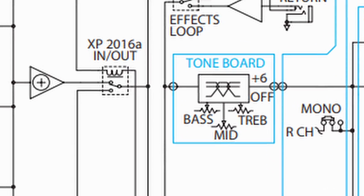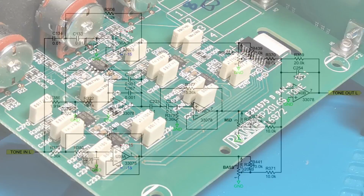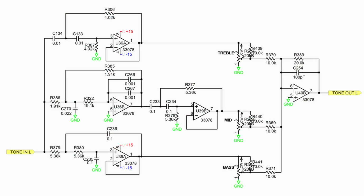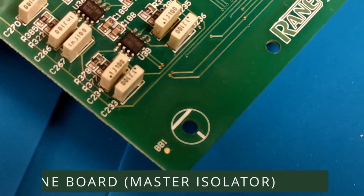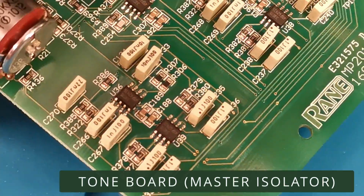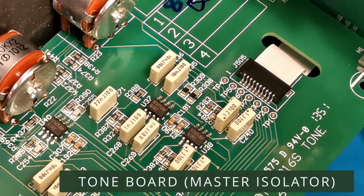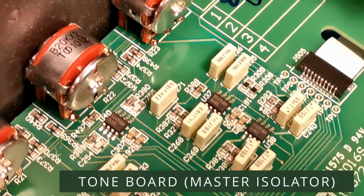It has an Isolator EQ control on the sum. The Isolator EQ is based on active filters that chop the audio signal into 3 bands and then sum them again. I've already made a video that contains a detailed explanation of this topic. As you can see, the capacitors in the filters are film type, but it's hard to determine what kind of film they use.